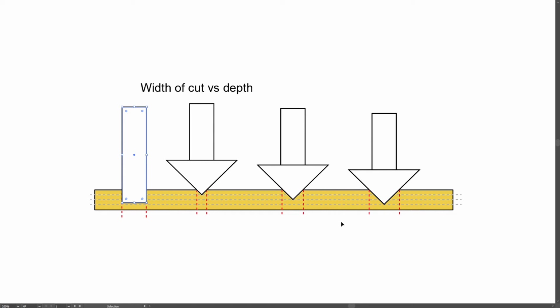But also remember that if you're using a smaller machine, then more pressure is going to be put on the bit, because there's going to be a lot more force on the bit itself. So sometimes you may have to make a decision as to what you are trying to achieve, whether the width of the cut is important or the depth of the cut is important.